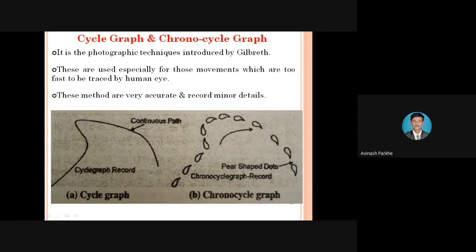We keep those pins on the board, the whiteboard we have selected for the demonstration purpose, and on that board you have the layout of your plant, in which all the machines or workstations are to be recorded. By using the string, we can measure the actual distance traveled by the material or by the operator. Through this string diagram, you can identify the critical movements or critical paths.